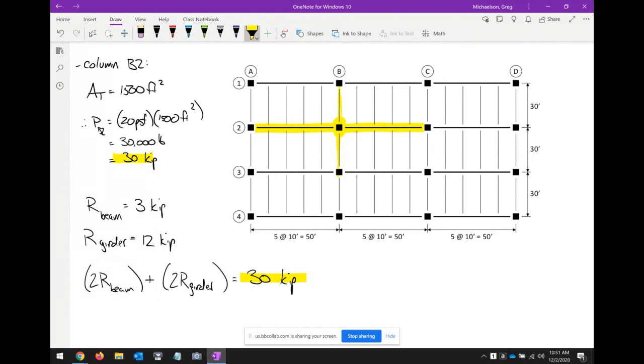It kind of puts into perspective how one PT cable handles 27 kips of force, one cable. Well, to give you some numbers, regular old everyday structural steel, A992 grade steel, has a yield strength of 50 KSI and a tensile strength of 65 KSI. Some pre-stressing strands have an ultimate tensile strength of like 270 KSI. It's crazy how much force they can withstand. They experience a significant amount of load.